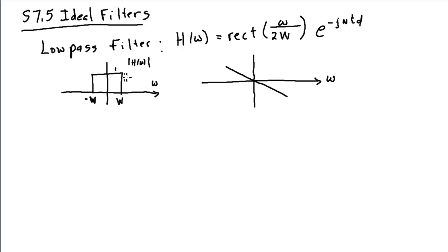So again, two main applications of low-pass filtering: passing through our signal undistorted and removing interfering signals and/or noise that's present, and/or possibly removing high-frequency components from our signal and smoothing our input signal, resulting in distortion, but in this case, desired distortion.